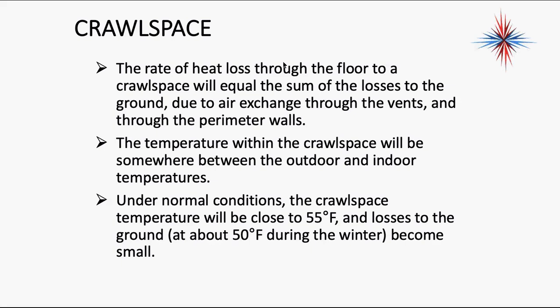As a service technician, you're going to occasionally have the opportunity to work in a crawl space, because that's where they install the furnaces. Now again, furnaces at 55 degrees, you're fine. But if someone installs a high-efficiency gas furnace in a crawl space that drops below 32 degrees, the condensate is going to freeze up and you're going to have a service call. So again, it's very important to realize that these crawl spaces can freeze on really cold, windy days.